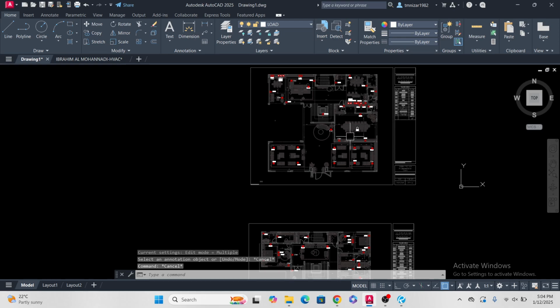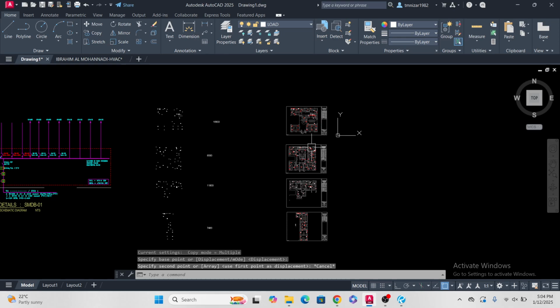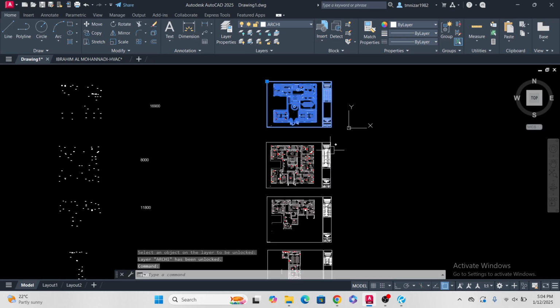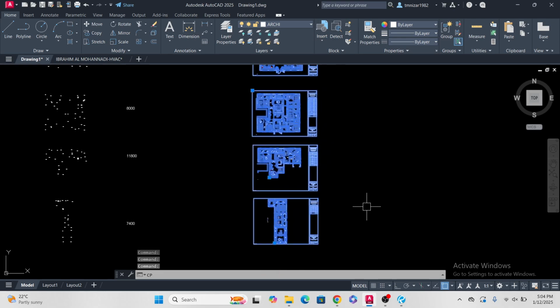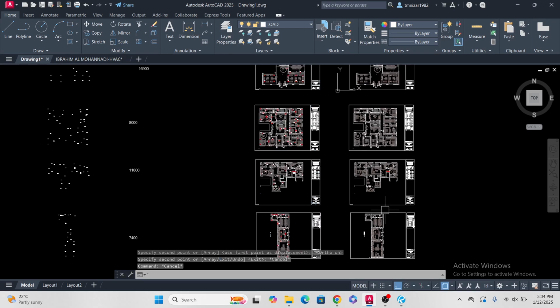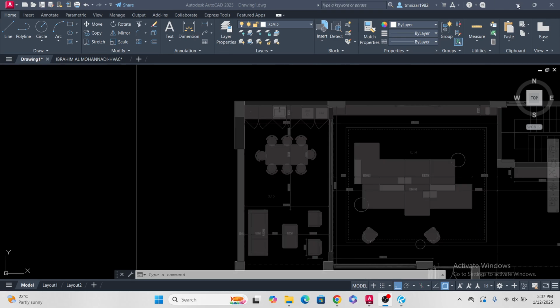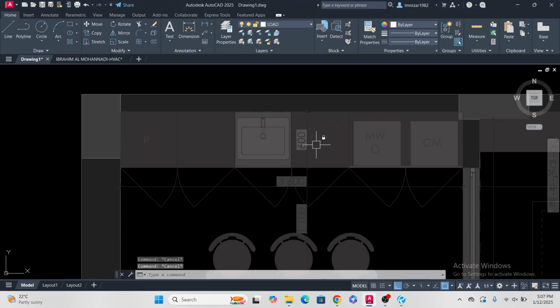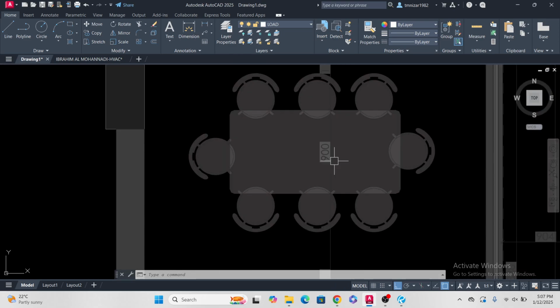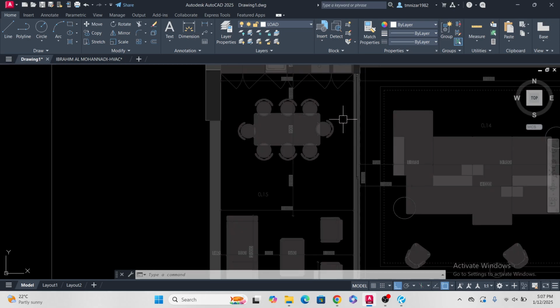So for the light, we have to add. I will just copy this one. This is a thumb rule calculation, not actual. So let's calculate the light. In this room, maybe we can use pantry light, 2 numbers. And here we can use 2 drop lights, like pendant lights, so 4 numbers. And we can use some small spotlights, 1, 2, 3 here, 1, 2, 3 here, so 6.